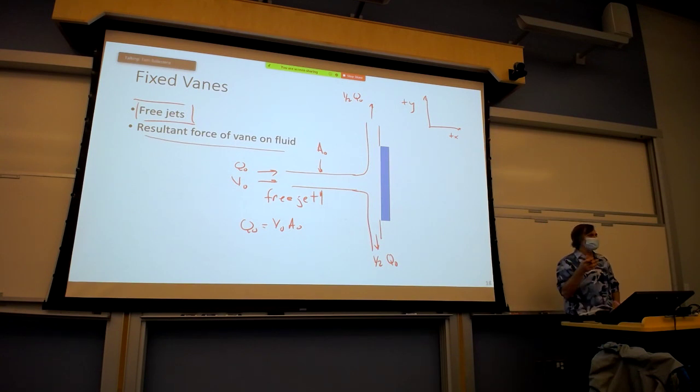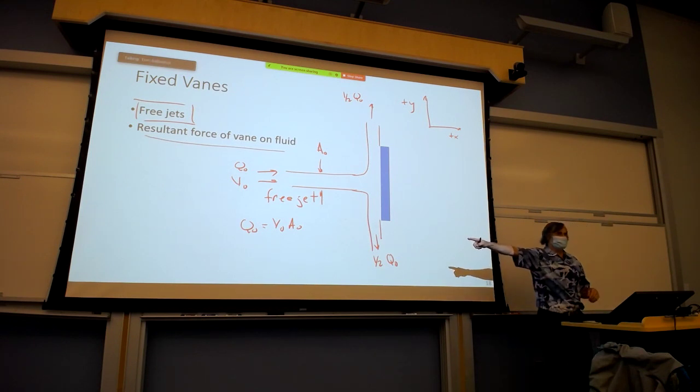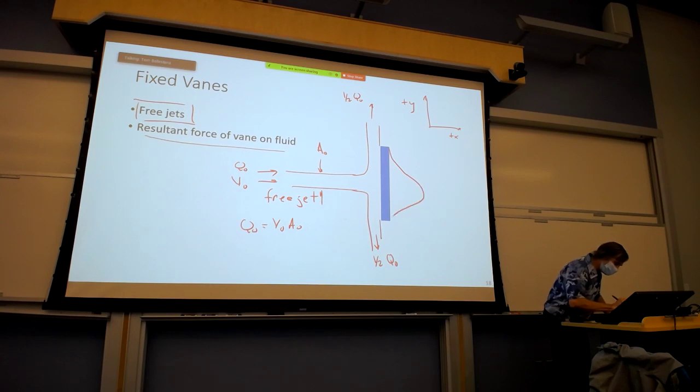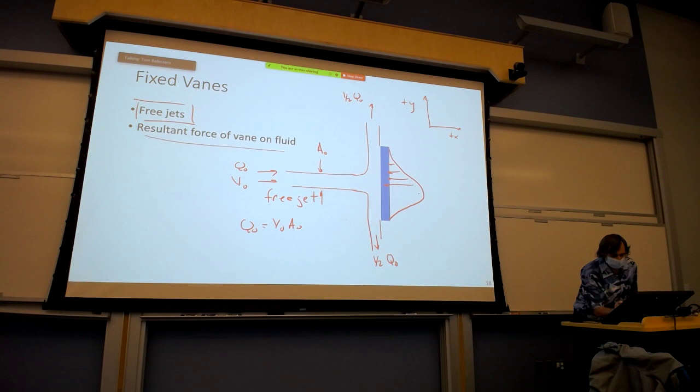Simple question. Is there a dramatic change in the geometry of the flow field in a short distance? Yes. If you didn't have that plate there, this fluid would not be splitting like it does. It would just keep going in a straight line. And in fact, if nothing was holding that plate in place, would it stay there? No. So what's happening is there's some nonlinear pressure distribution on the backside of this plate pushing against the oncoming jet.